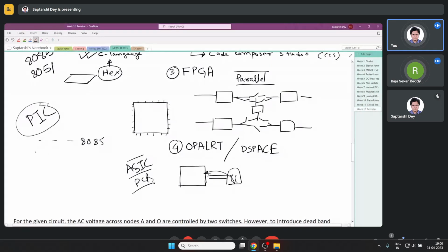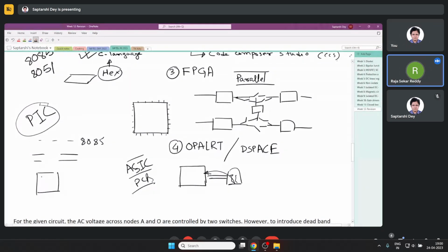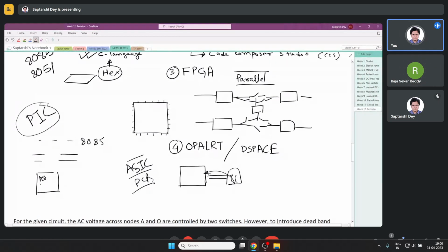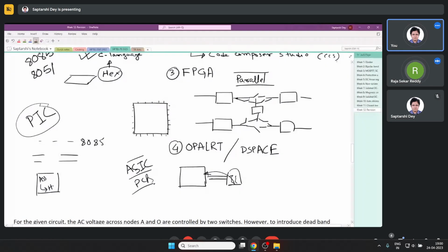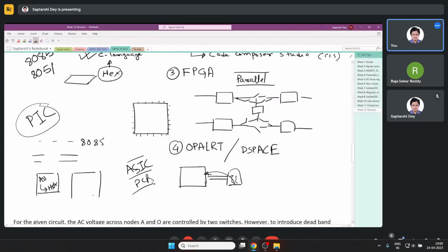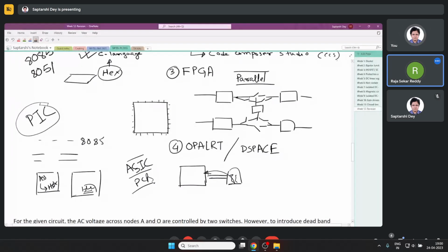So we used to write the program in assembly first. Then there was a table that will give you the relation between the assembly mnemonics to the hex. Then we would translate it to hex looking at the table, then directly feed the hex numbers to a trainer kit using 1 2 3 4 ABCD and all.